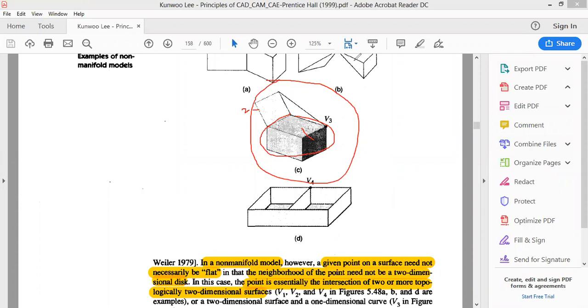So in this case, when the design person goes for analysis, what is going to happen is that, as we all know, whenever we do any type of analysis, we have to use suitable mesh elements. So here we can use solid mesh elements since it is a solid. But we cannot use the same solid mesh over here also. The data is going to be different, our analysis results will vary, right? Because one is a manifold model, the other one is a non-manifold model. So we cannot use the same mesh type over here, since it's got a very small thickness.